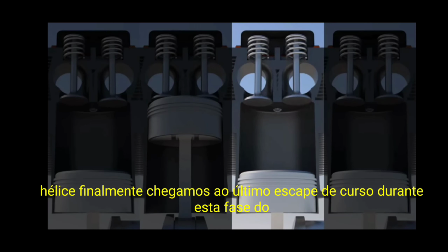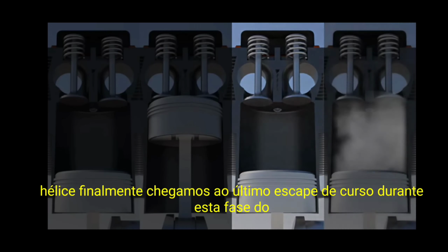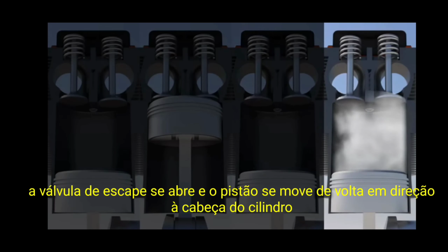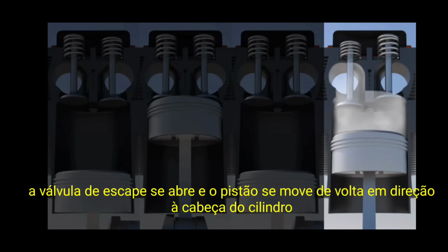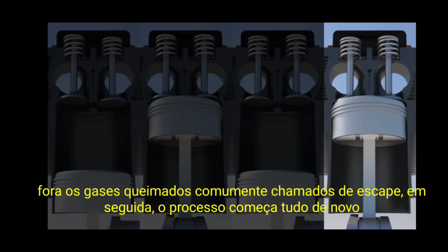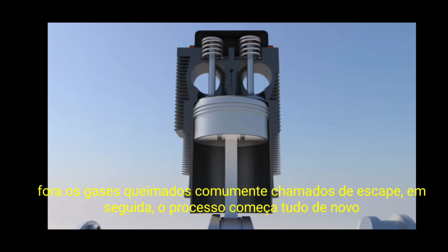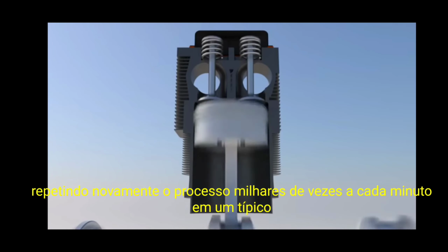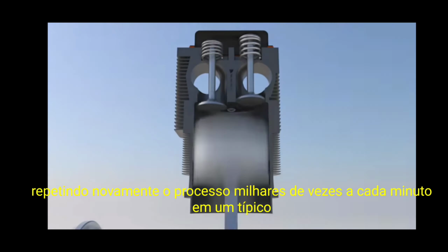Finally, we reach the last stroke, exhaust. During this phase, the exhaust valve opens, and the piston moves back towards the cylinder head, pushing out the combusted gases commonly called exhaust. Then, the process starts all over again, repeating the process thousands of times every minute.